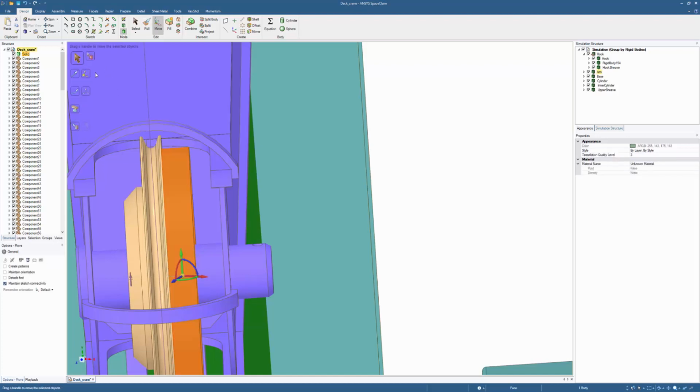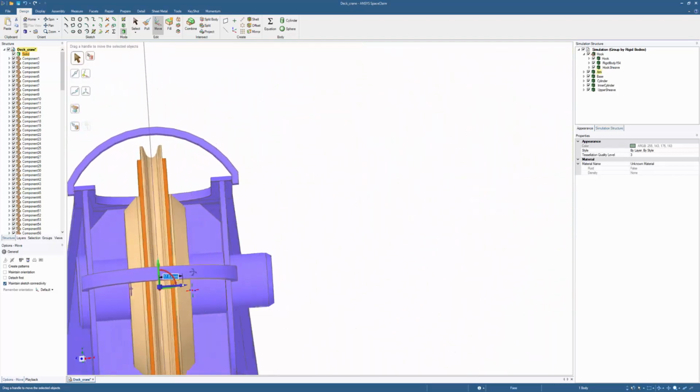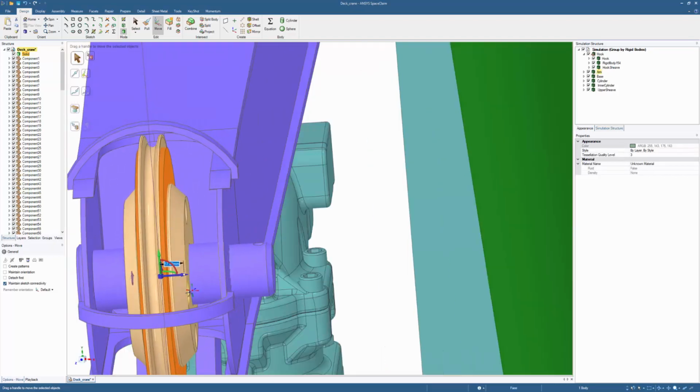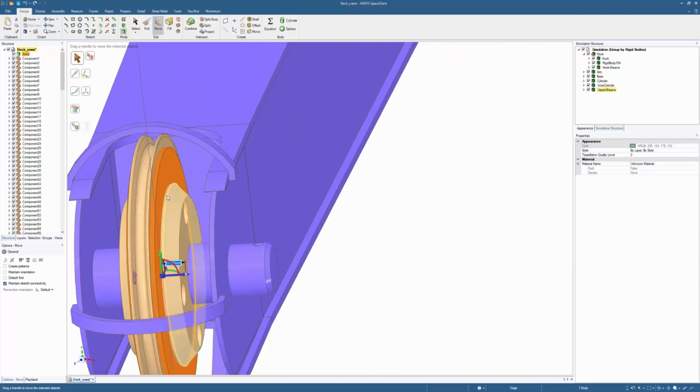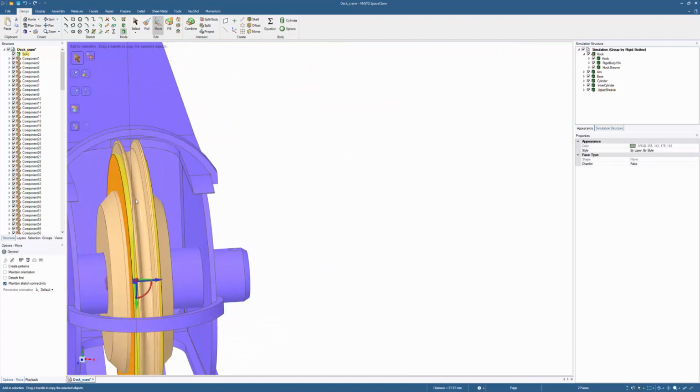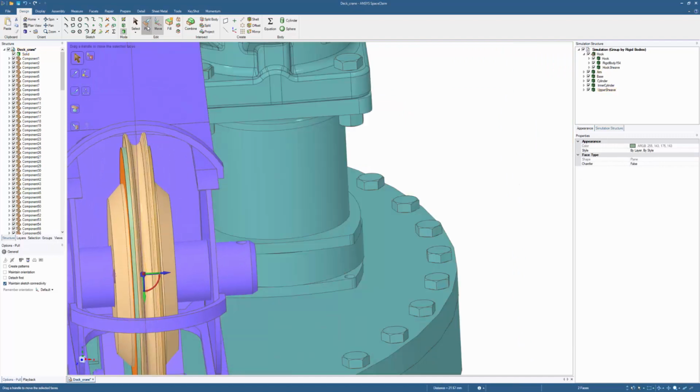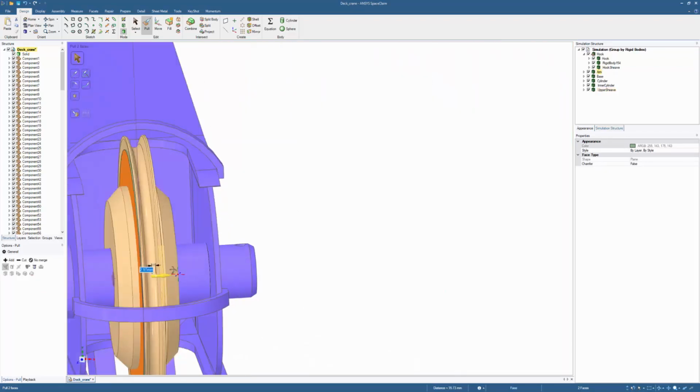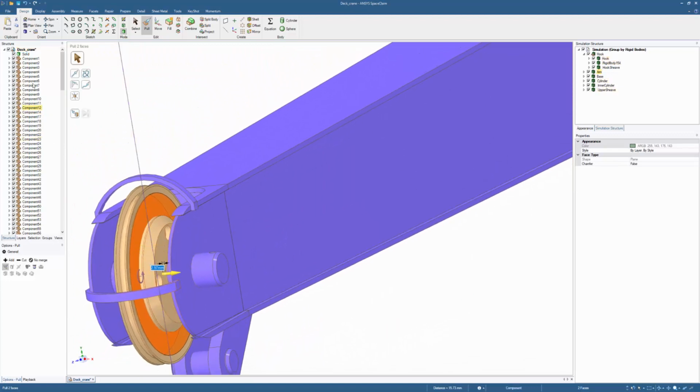And later I will show you how to disable collision with the tri-mesh and only have the collision available for the primitive, so that when the wire is colliding with the sheave, it's actually colliding with this cylinder primitive instead of the triangle mesh. And that will give you faster and more robust simulation. We can adjust the width by using this pull tool so that it's according to the original triangle mesh.